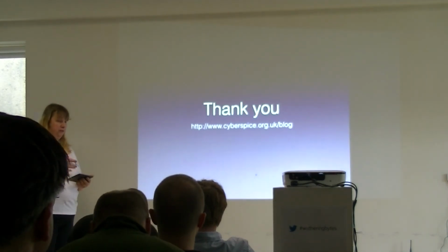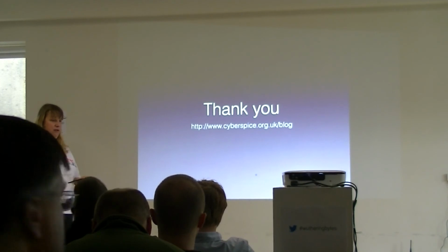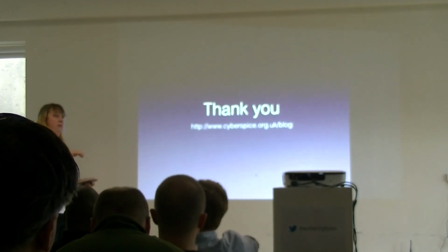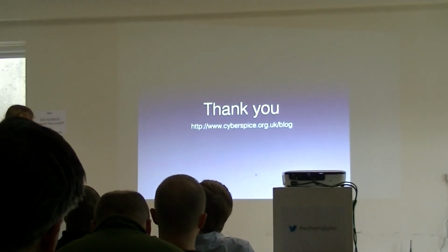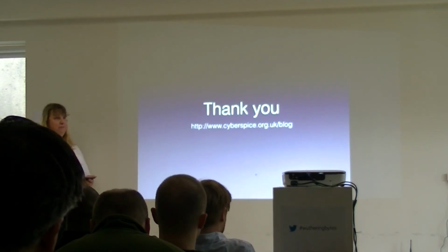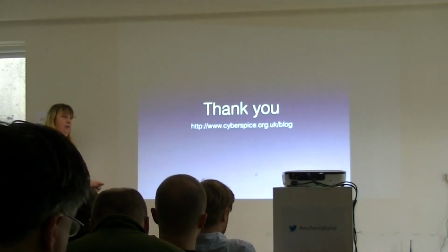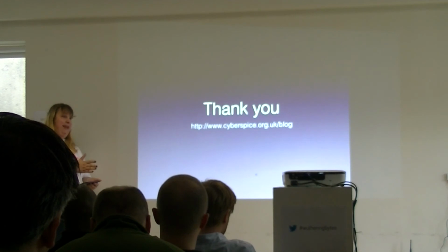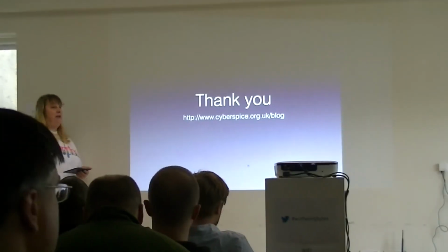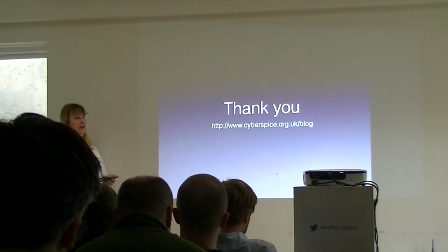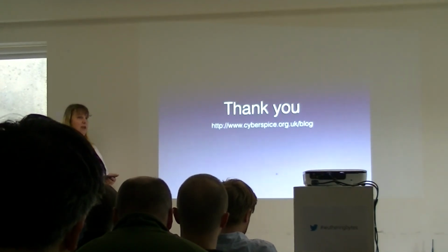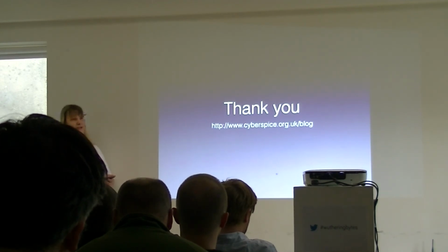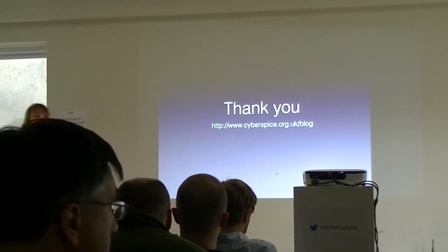But you'll just basically use your I2C bus and read from a register. What I didn't go into there is the I2C protocol actually allows you to read from multiple registers consecutively. So if you go to register 10 and read 2 bytes, it'll read the byte from 10 and then the byte from 11. So you might find for a 16-bit analog to digital converter, it's actually a 16-bit register. So you say, I'm going to read from register 10, but you actually read a couple of bytes, and it reads 10 and 11, which give you the 2 parts of the 16-bit value. Thank you.